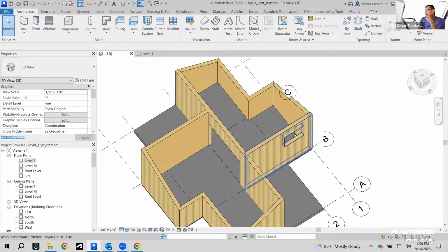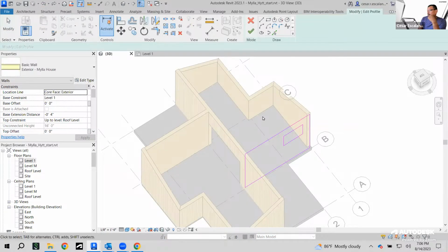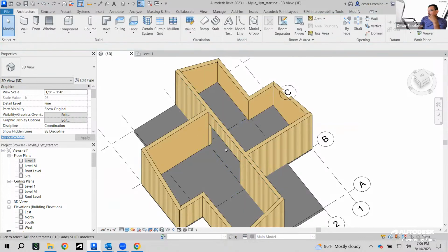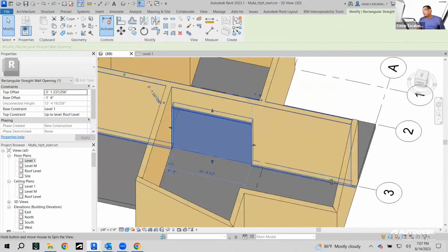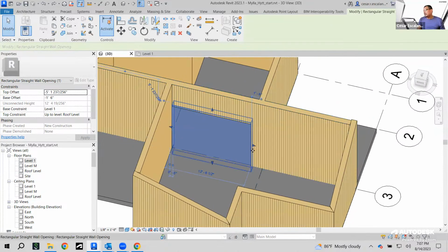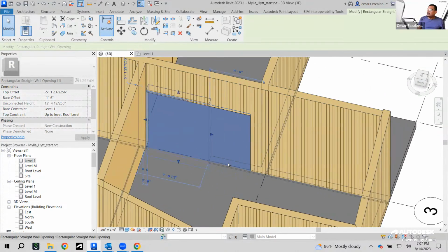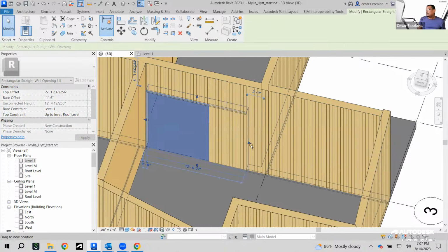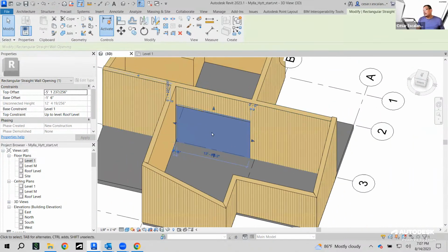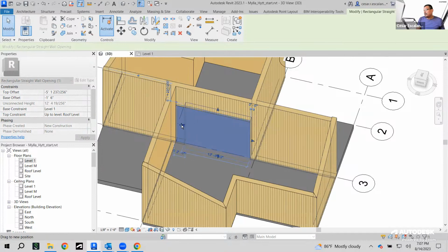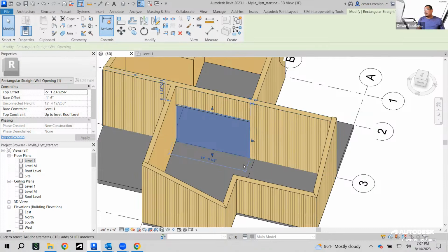So if you need to change the opening, you have to edit the wall. In the other method I just showed you, this wall opening is an individual entity, a void intersected with a wall, and it can then be manipulated individually to generate a space. To build soffits in walls, I like this method. Again, it's a preference. This wall opening only affects the wall.